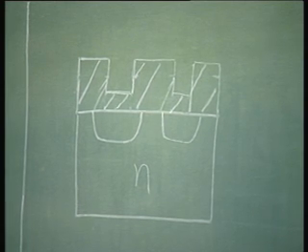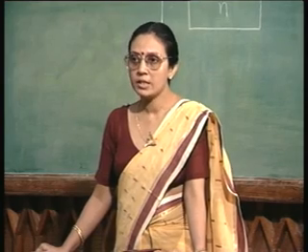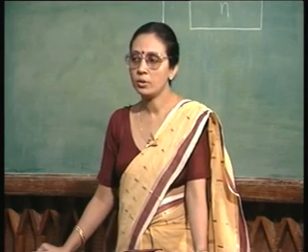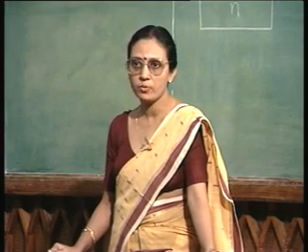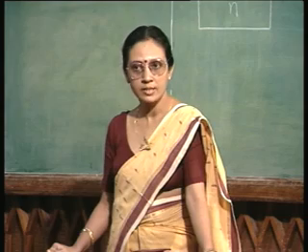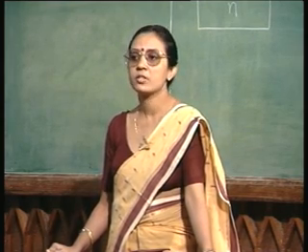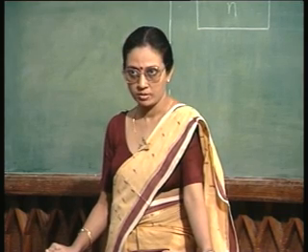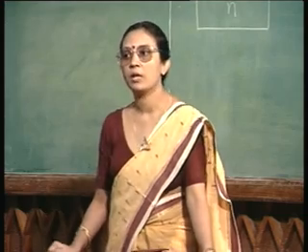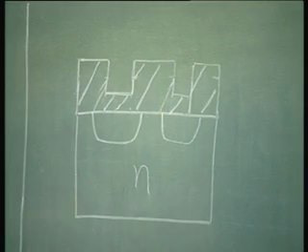So, a MOSFET has, apart from source and drain, a third contact, that is the gate contact. Okay. So, I need to realize the gate. You know, the MOSFET gate is the heart of the device, that is, this is where we have the metal oxide semiconductor structure. So, in order to realize the gate, first of all what we have to do is to do the gate oxidation. Now, here comes a question. I already have an oxide between the source and drain, right?